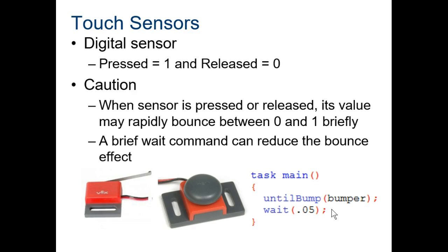So explore the different commands. The last thing here is touch sensors. These are basically just buttons, and the little cautionary statement is about something that's called key bounce. When you press a button, there's a little time when you're pressing and when you're releasing where it sends a lot of different values. So what we do is we build in a little tiny wait command before we check it again, and that way when you push it, it's going to have one response, not 100.